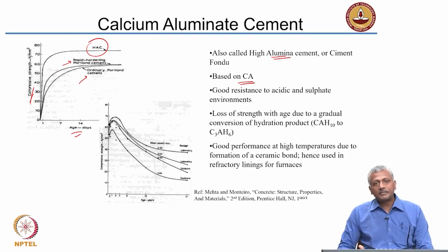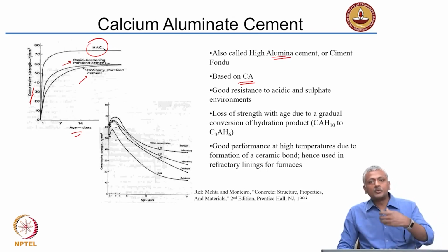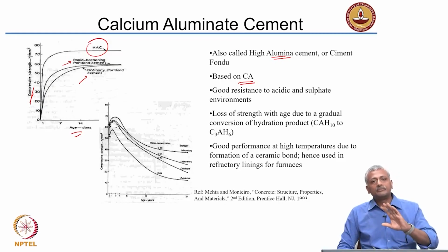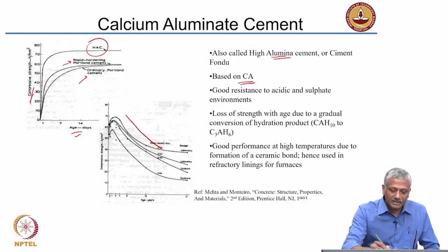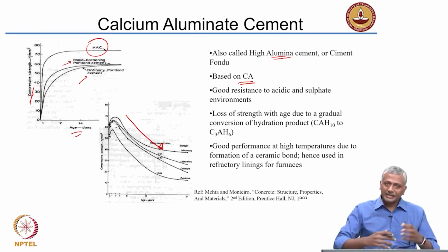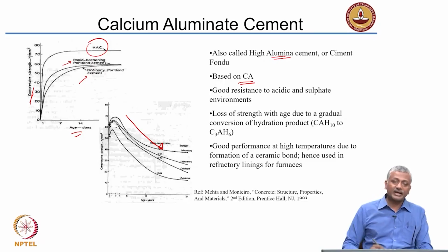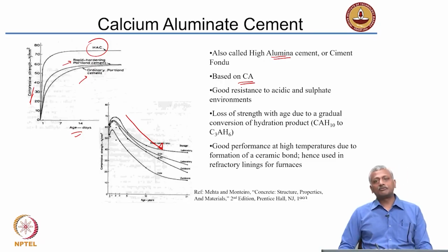Right? So, they started developing a lot of structures with high alumina cement, which gained strength rapidly. The problem was, as this concrete made with this cement was exposed to the external environment with moderately high temperatures and humidity, the strength basically dropped over time. Okay, this happens because of an internal chemical compound composition which is changing as it is subjected to continuous exposure to temperature and humidity. And because of that, you have a problem of using the cement for normal construction.